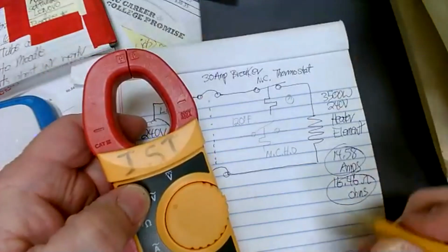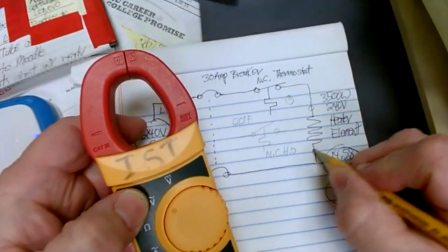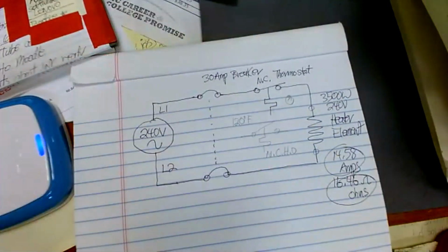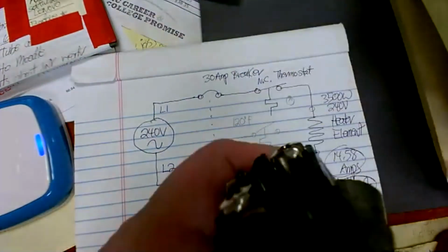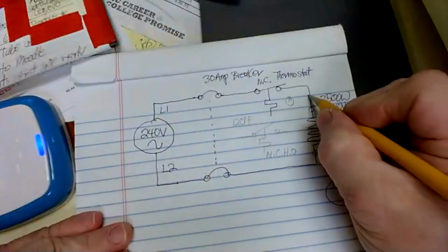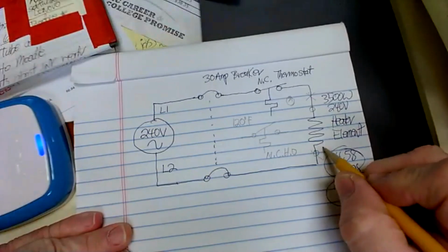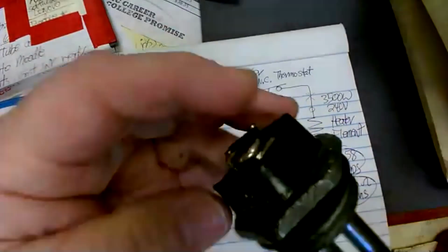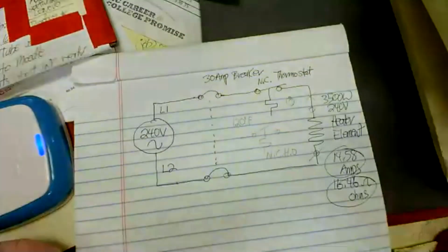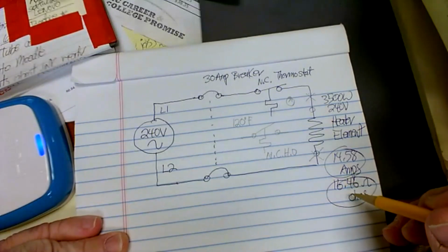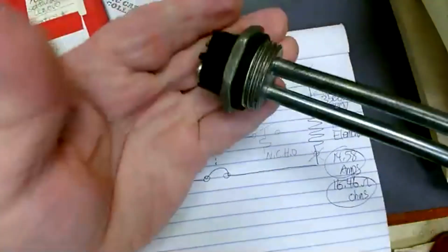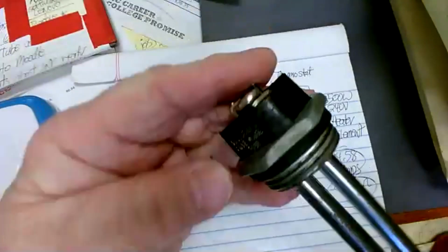If it's dead when you check volts, remove the wires. You've got the screw terminals that are right here. You would take the wires completely off of them. I'm going to put X's there. You would disconnect it, and then you would check the resistance, the ohms, like we did a while ago, and see if you are getting close to that. And if you're not, then it's definitely bad and you just go get another one of these, okay?